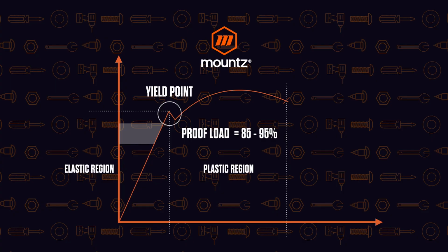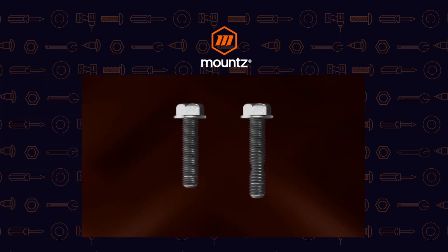And we see torque failures sometimes when we push a fastener and it gets over torqued, or we apply too much torque to it and it moves the fastener close to the yield point. Then any type of shock or vibration can cause that fastener to break because it is at or past the yield point of that fastener. So that is typically where we want to be as it relates to the fasteners, but that is how tension is working within the actual fastener.